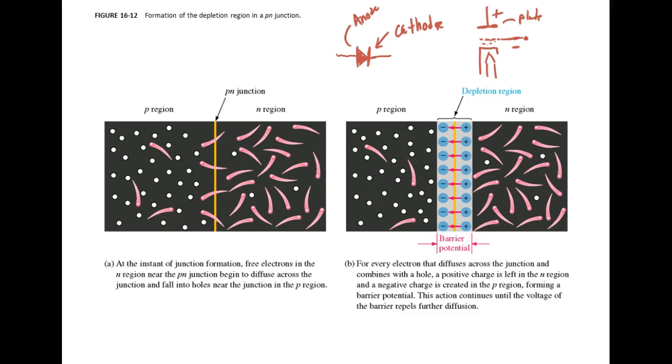And these terms came from tubes. I'll show you how to identify it on these diodes that we get. Everybody okay? So this is going to set up a barrier potential, and for silicon the barrier potential is going to be around 0.7 of a volt. Some books teach 1.0, some books teach 0.7. Now you can't get any work out of this because it's got a high resistance, right? But if we had an extremely high resistance meter, we could literally measure this.